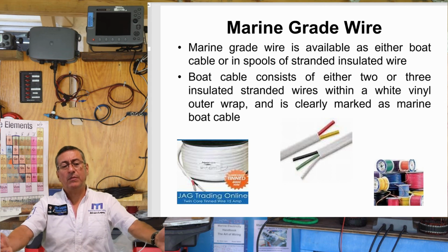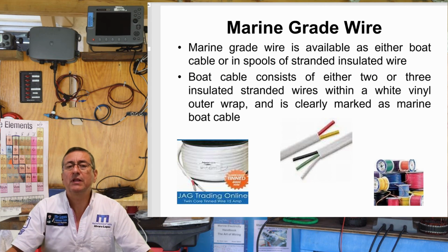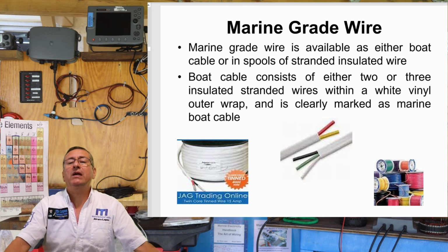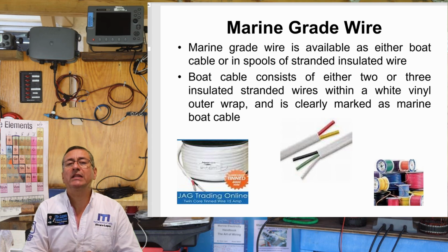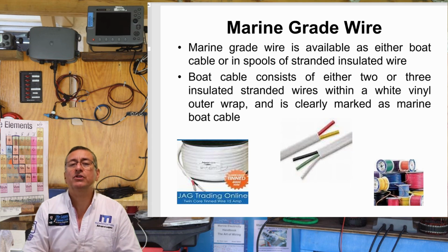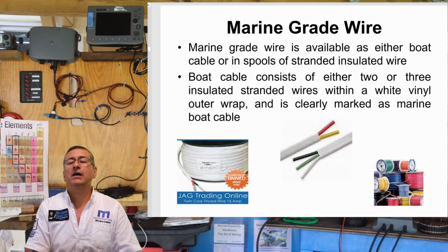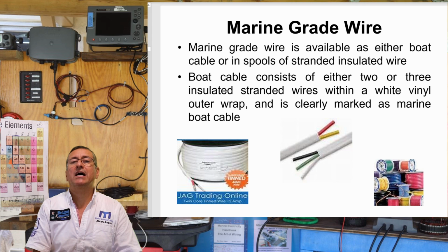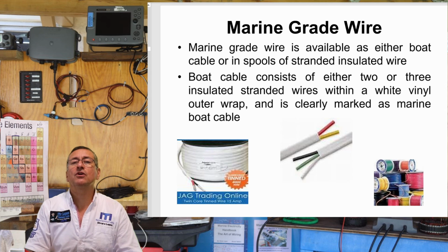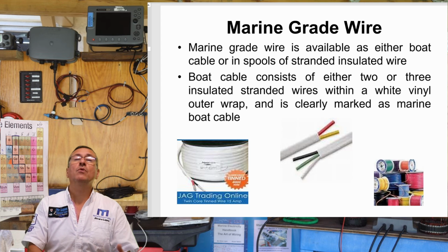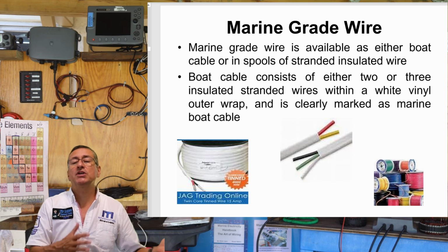After that, we are going to talk about marine grade. The marine cables should be marine grade, marine approved. And we are going to always use marine grade cables. Never use industrial cables, never use residential cables, because those cables produce excessive resistance and corrosion, and those cables are not accepted. Probably if you use those cables, your installation is not approved, and probably you have a complaint, and you need to remove the equipment and do the job again.